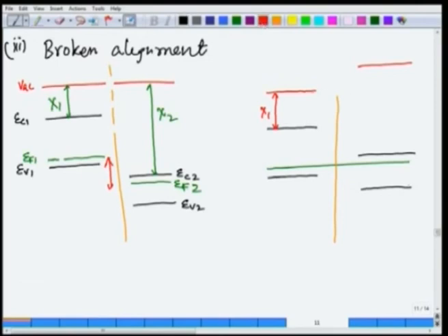Again the same thing, smoothly join these. Join this vacuum level. This is my vacuum level. Smoothly join it, and now use these xi's for the material. They must remain the same. Now it's easy. So this material should go exactly the same way. Right here, it should go up. So this material should also go up, following the same way so that this band gap remains the same. Eg1 remains Eg1, and what happens to this material? For this material, this must go something like this and something like this. This should bend something like this, because it should follow,